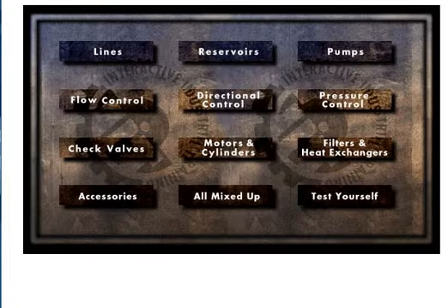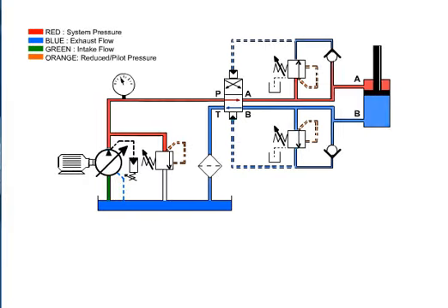In this learning lab, you will learn the proper name. A schematic is a compilation of graphic symbols interconnected, showing a sequence of operational flow. In short, they explain how a circuit functions. Correct schematic reading is the most important element of hydraulic troubleshooting. Although initially most circuits may appear complicated, recognizing standard symbols and systematic flow tracing simplifies the process.